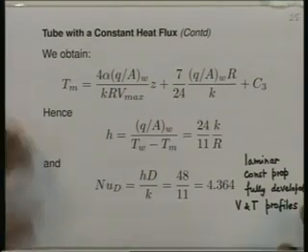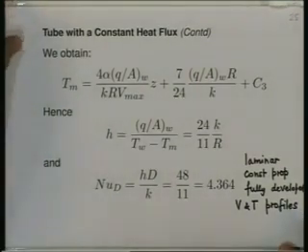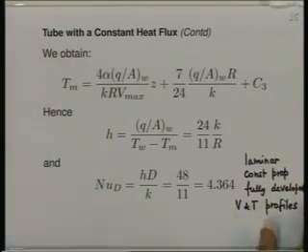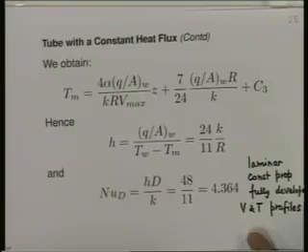This is where the problem which we started to solve, determine the Nusselt number for a fully developed flow, laminar, uniform heat flux, ends. Let us look at the constant wall temperature case. In this case, an analytical solution can be obtained, but the algebra and calculus is not as simple and straightforward as that for the constant heat flux case. If you look up some advanced book on convective heat transfer, you will find this derivation there.